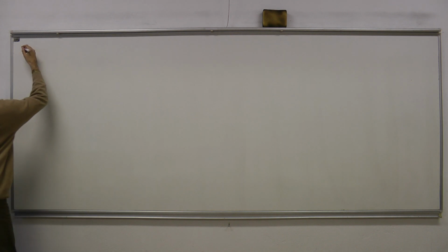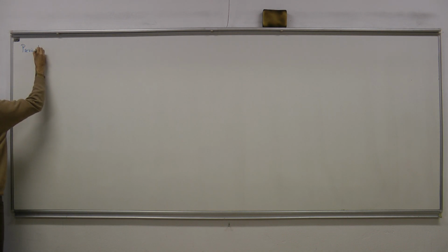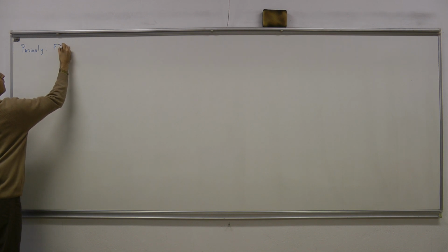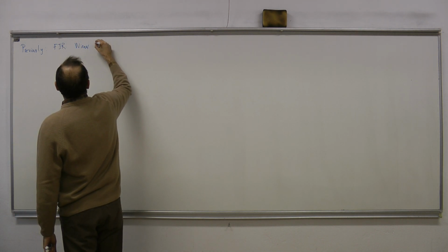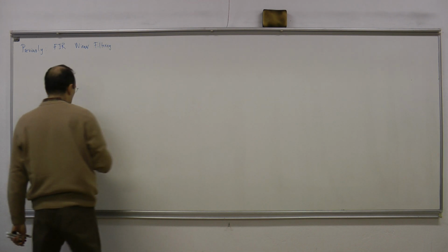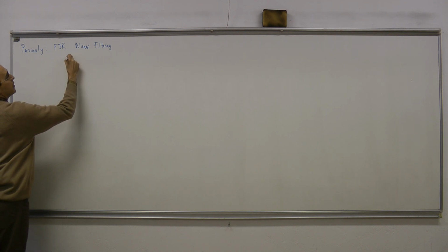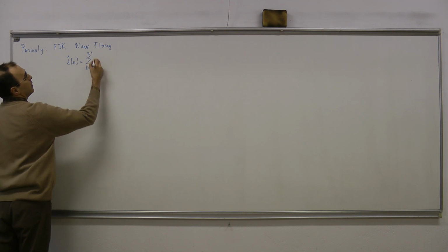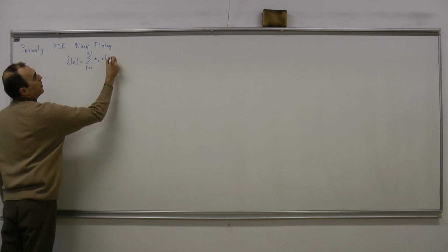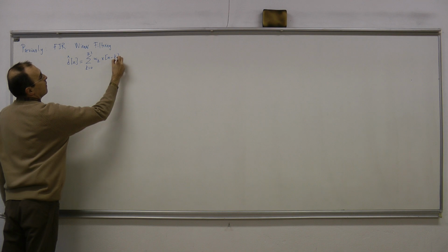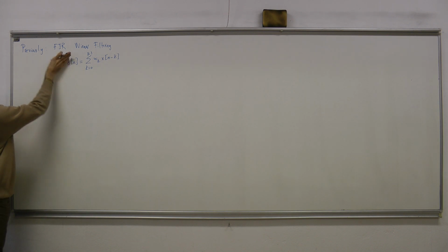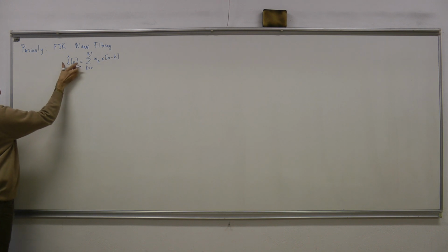Okay, so we are continuing with Wiener filtering discussions. Previously, we have discussed FIR Wiener filtering. So what do I mean by FIR Wiener filtering? There is an estimator. This estimator is simply a linear combiner of the last p samples of a process. Okay? So this is like a convolution type of relationship. It's a linear combiner. So the goal is estimation of this process d[n] with this estimator d hat of n.